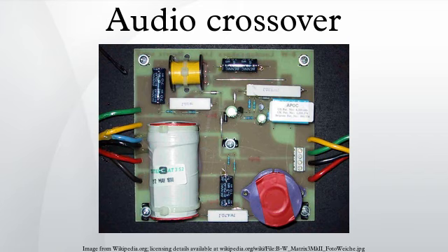Crossovers used in loudspeaker design do not require the filter sections to be in phase. Smooth output characteristics are often achieved using non-ideal, asymmetric crossover filter characteristics. Bessel, Butterworth and Chebyshev are among the possible crossover topologies.